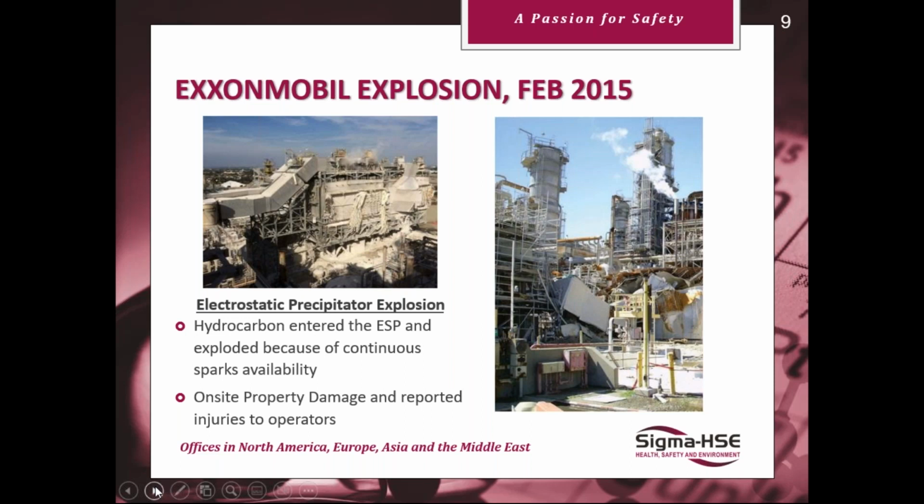They failed to identify how hydrocarbon vapor could enter into the ESP. And once it did, the inevitable happened. The continuous sparks were of sufficient strength to ignite the atmosphere. This caused on-site property damage and injuries to operators.